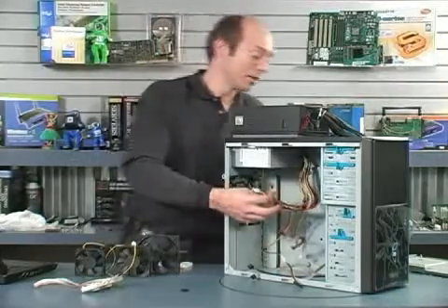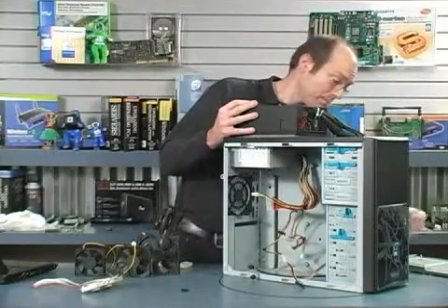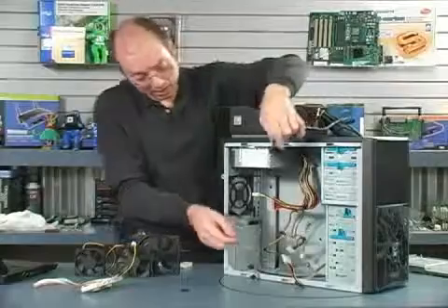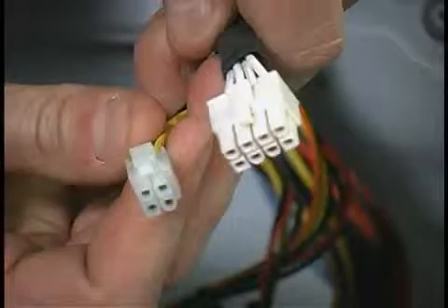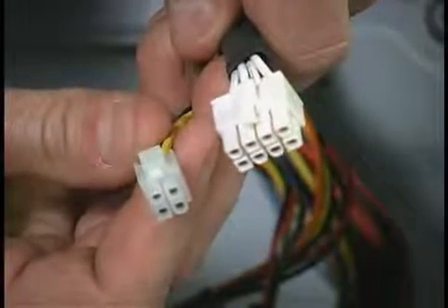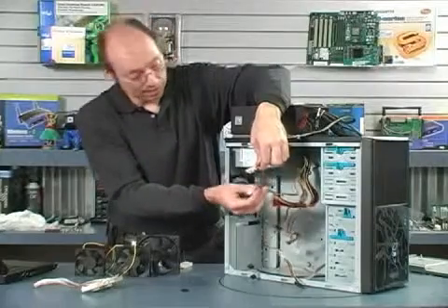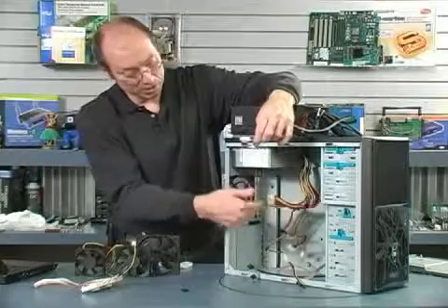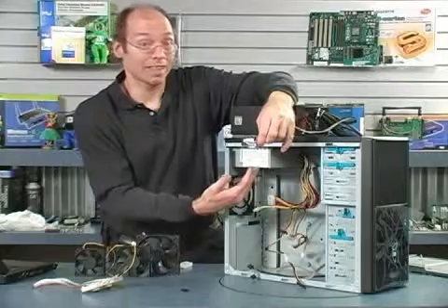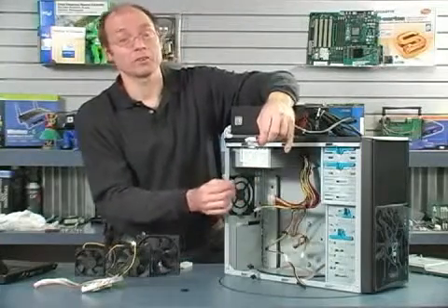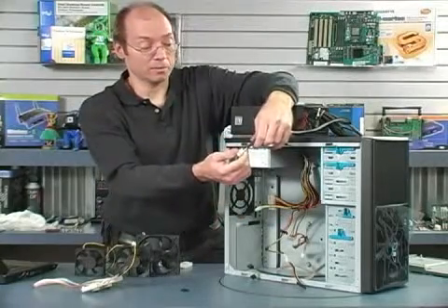So what you'll want is to find a power supply like this one. This is a bigger, heavier duty power supply I have on top here. And this one has an 8-pin motherboard CPU power connector. You can see the difference here, 8 pins versus 4. Now you can get adapters to turn the 4-pin into the 8-pin, but that doesn't provide more power. So the idea is that if you need a bunch of adapters to make your power supply work with what you have, you probably don't have an adequate power supply to begin with. So while an adapter here and there is okay, if you start using adapters for everything, it just means you don't have an adequate power supply.